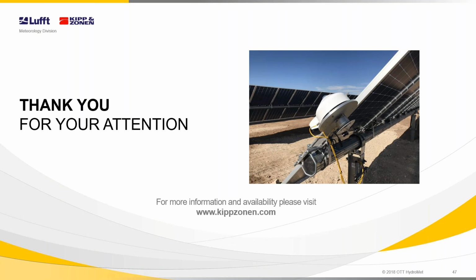Thank you, Mark. And there's another question. For rearside irradiance measurement, can a solar reference be used instead of pyranometers? Yeah, there are two schools of thought, and in the standard there is the possibility to measure with a pyranometer or with a PV reference device, and it would depend on which school of thought you want.